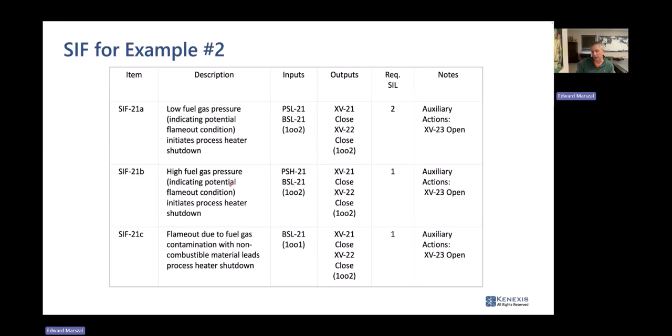If you've defined your hazard as flame out, then yes, you can. But if your hazard is actually an overloaded, bogged firebox, then you cannot include that measurement. So hopefully you're catching the overarching message here, which is, what is the actual hazard that I'm trying to detect, and what are the sensors in my logic solver, all of them, that are capable of detecting that hazard is present.